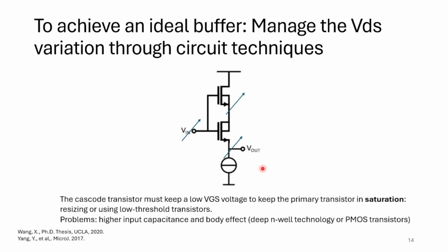There is another example from 90 which has been repeated in this paper and thesis. If I remember, they call it a cascode source follower. In this case, they limited the drain source variation, which causes channel length modulation, by using this transistor. So when this goes up through this transistor, these parts go up, and the drain source of the main transistor follows each other.